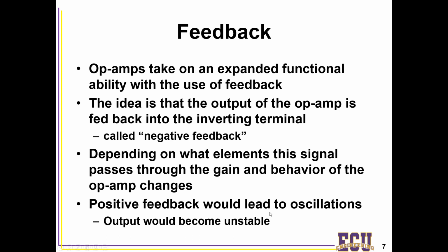Positive feedback actually leads to a lot of oscillations and helps the output to become unstable. Positive feedback, as an example, is if you've ever been to a concert or seen somebody make an announcement and they happen to have a microphone right in front of a speaker. Well, sometimes you hear that reverberation where it just gets louder and louder and louder and becomes unstable and ultimately squeals.